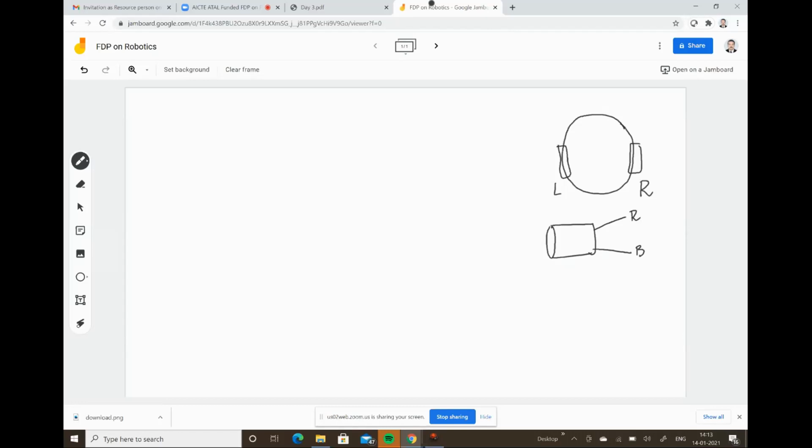Here the table is generated by assuming that we have four connections: PA0 and PA1, that is the left motor, and PA2 and PA3, that is the right motor. If I need to rotate both motors in the clockwise direction, I'm assuming the red wire of both motors should be supplied with logic 1, that is, the VCC to the motor applied to the red wire.